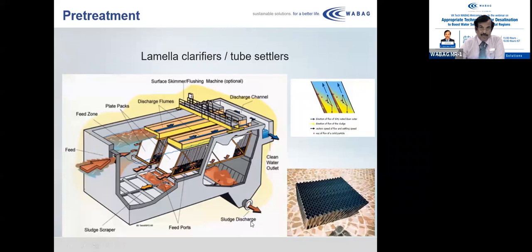We were able to settle down all the TSS, total suspended particles, and remove them. The only thing is we are forced to evacuate the sludge not every 12 or 24 hours, but once in 3 or 4 hours. Otherwise, the hoppers get filled very fast.